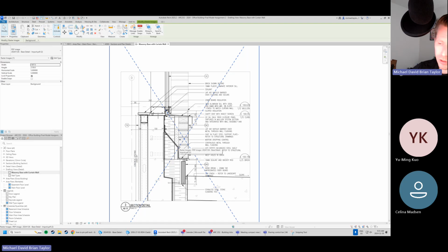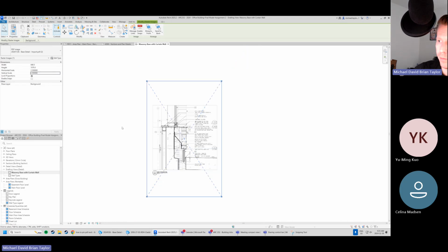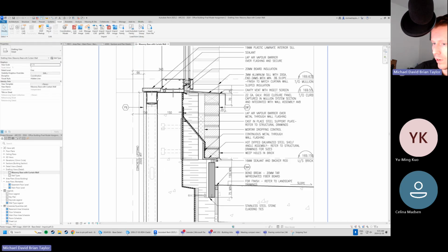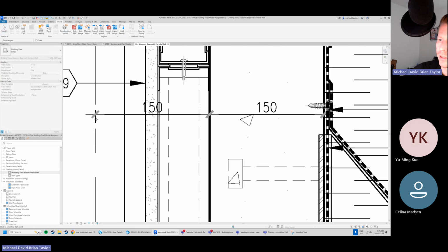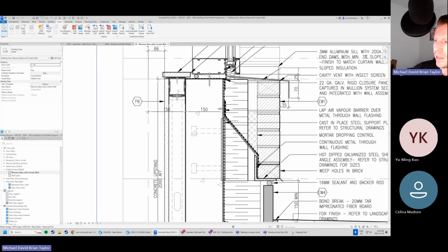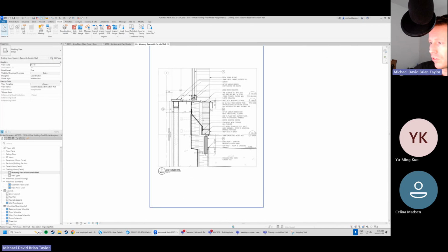Well, you can, of course, do it outside of Revit, and you can import a half scale drawing. So if I was to take the other one and scale it and then import it. Conversely, we can also change this to be half the scale, right? So if I'm going to make this a 1 to 10 drawing, it's going to get smaller. So I'm going to make this 2.5 by 2.5, and now we have a 1 to 10 drawing. So if I come back in here and I make this 1 to 10, if this is 50, this should actually now be 75, but let's just double check, right? So roughly 75, 74.1 here. Right. So instead of this being 1 to 5 now, this is a 1 to 10 drawing.